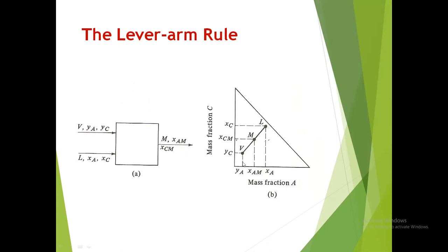Now, what is this inverse lever arm rule? I'm sure this is not the first time that this was discussed to you, the inverse lever arm rule. This is partly graphical, so that is why I'd rather have you do it analytically all the time, because it will entail that you have to rely on what you have on the diagram and then read compositions based on the lines, the points on the lines that you have drawn in your diagram for your answer.